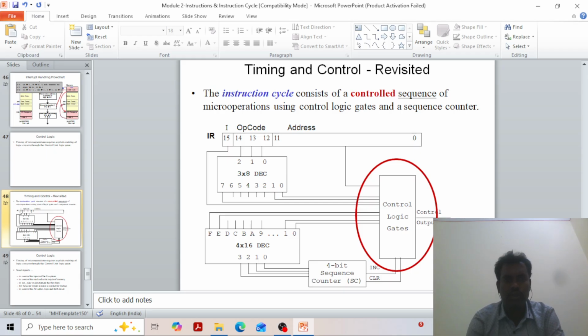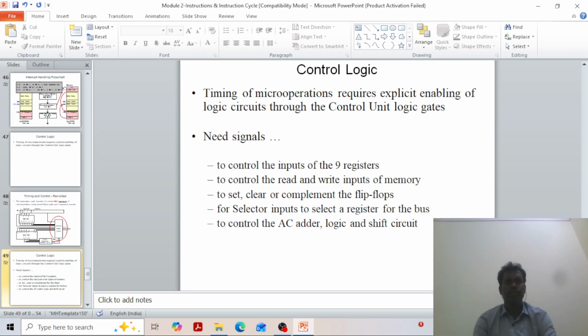The control logic calculates the different kinds of states, T0, T1, T2, by using some counter and additional decoding logic. This decoder will generate the particular state that the control will use, either T0, T1, T2 or T3.